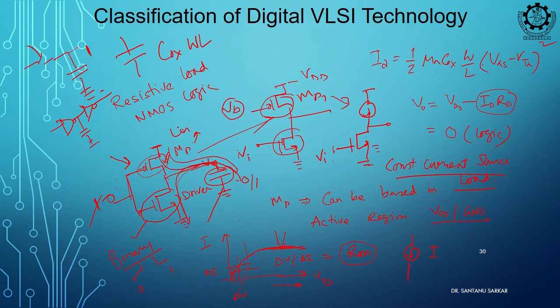Then this capacitance is a leaky capacitance. There will be so many parasitic currents, right. Through the parasitic connections, this current will flow and this capacitor voltage will be discharged. Capacitor will be discharged, and so this logic it was holding, it will try to fall. So, unless I refresh it again, it can't hold for long. This is the primary difference between the static and dynamic logic. Both the cases capacitor is there, but the connections, the style is different.